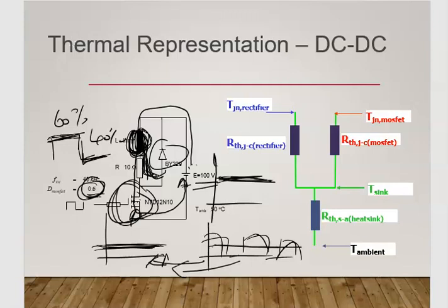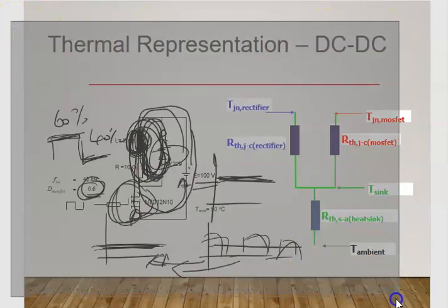So it needs a circuit to deplete the current. That's why we have the power diode, to deplete the current inside the inductor to 0, and only then is it safe for the next cycle to start. On through the outer loop, off through the inner loop. That is how the circuit operates.